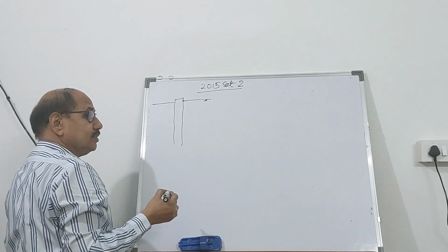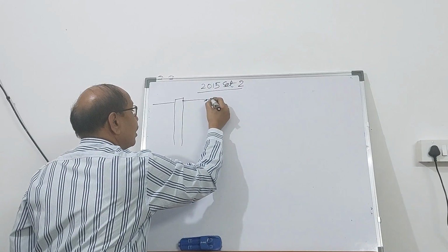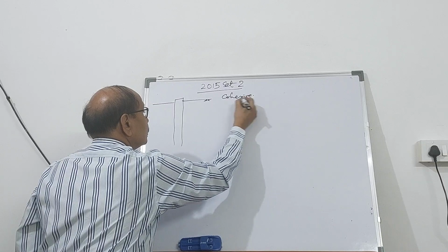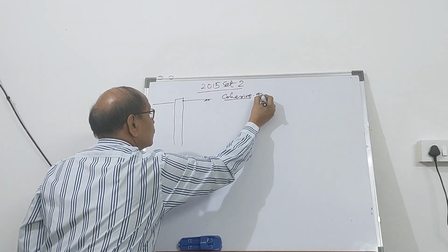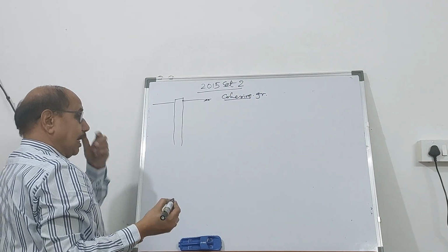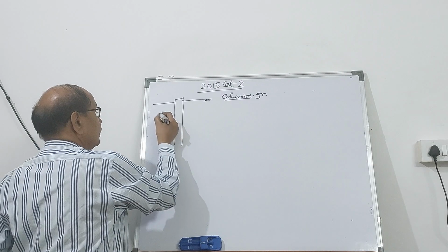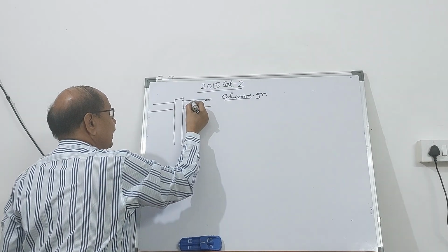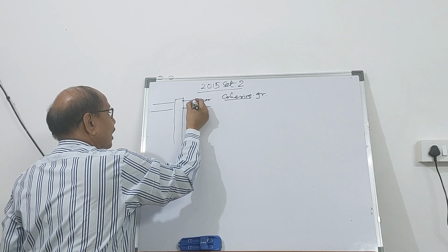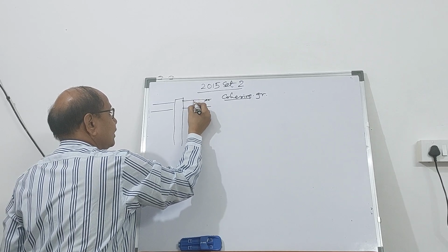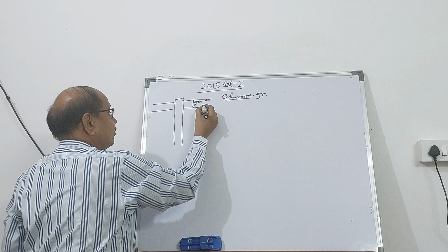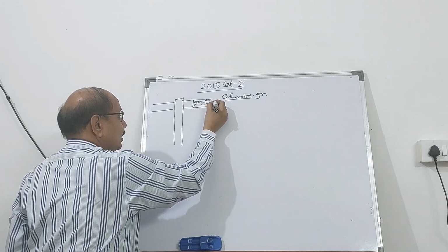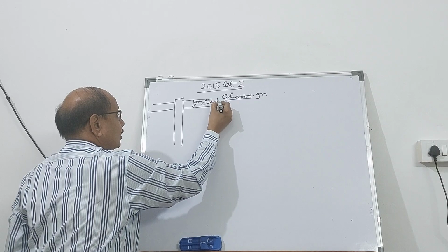The ground properties: it is purely cohesive ground, so the ground is cohesive in nature, and the value of C is going to change. For layer 1, which is of 5 meter, the value of C is known to you as 40 kilopascal.